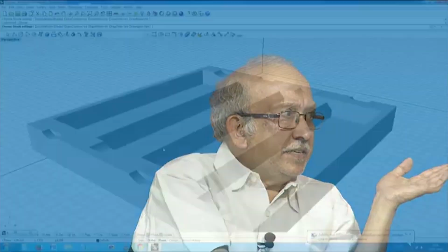Does it have a Gothic arch? Is it straight, or does it have the inverse hyperbola type of things? The profile makes a lot of difference, which you can choose depending on the type of machine and the material. You can play with it a lot. In this case, only for a sample I have made, I have just used a triangular profile.